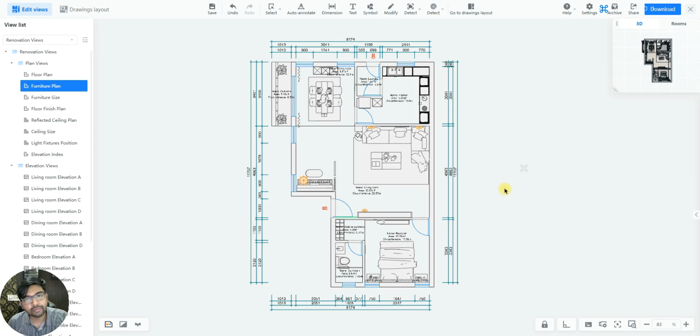And in addition to all these factors, always remember the fact that unlike your custom furniture drawings, which are generated for individual rooms within that floor plan, your construction drawing will be generated for that entire floor plan. So if you're planning to generate your construction drawing, make sure that your entire floor plan is actually modeled so that your 2D drawings will be proper. If you have some spaces in your floor plan left incomplete in your modeling, it will precisely be updated in your construction drawings as well. So make sure that you model the entire floor plan if you're planning to generate your construction drawing.